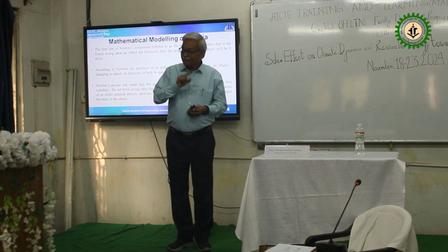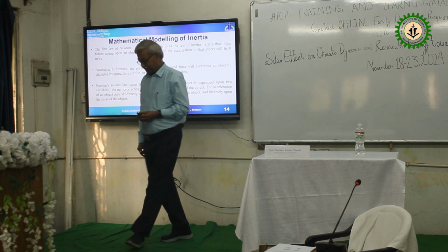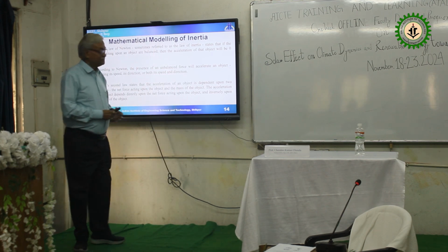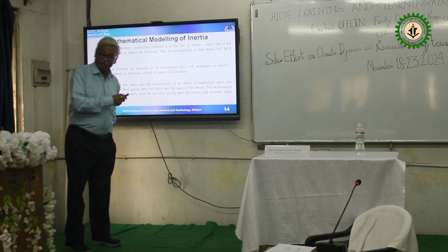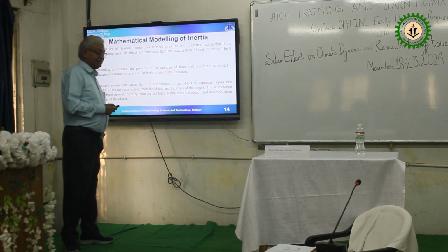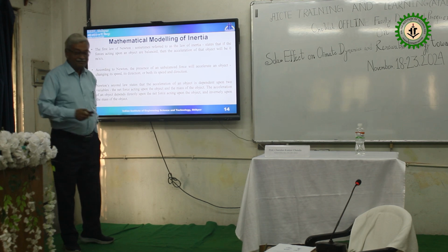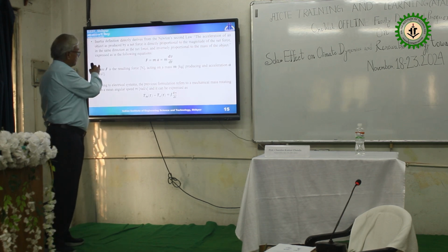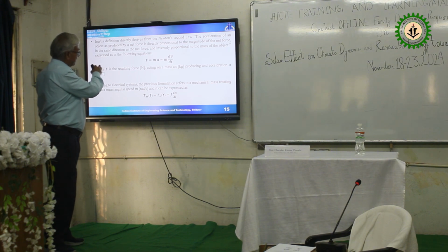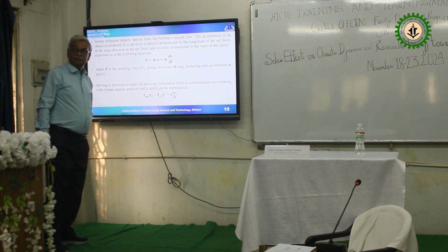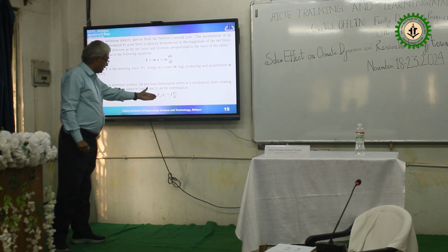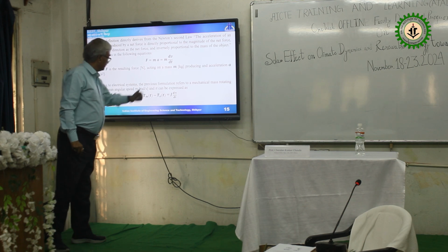So let us start from scratch with that swing equation. Slowly let us try to define it. It's all a little bit mathematical. In fact, I think I could have taken this one before lunch. Inertia definition: F is equal to mass into acceleration, m dv/dt. This is for linear motion. But as far as the rotational part is concerned, this m will be replaced by J and dv/dt by dω/dt.